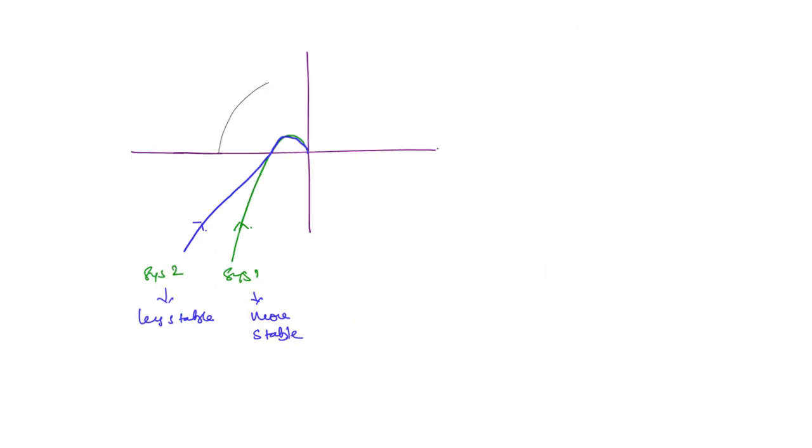You can understand the phase margin when you consider the unit circle. So that means this point here is -1, 0, this point here is 1, 0. You can write down here, this is the unit circle. Okay. Now what you do is you draw a line from the origin to the intersection of both the systems with the unit circle. Okay. So what are you going to see here? The system 2 can be rotated by this amount of angle before it reaches -1, 0.